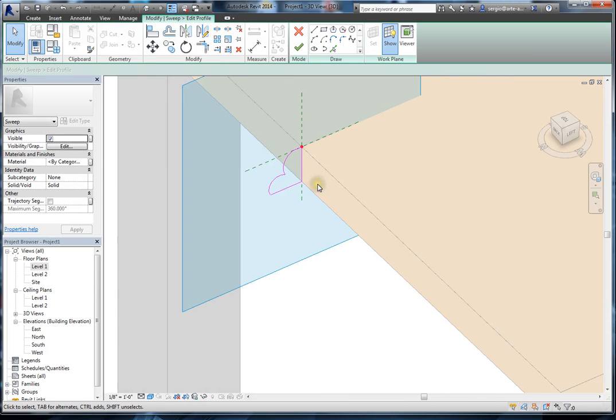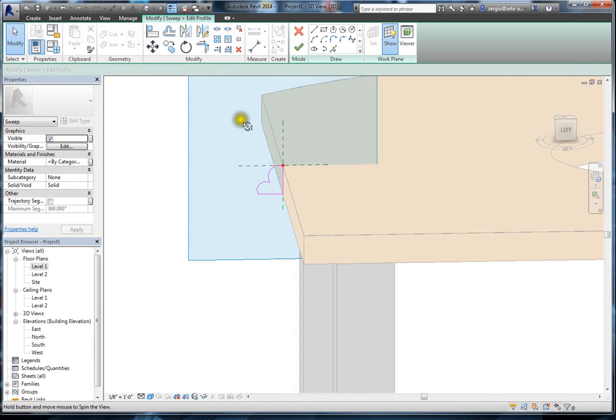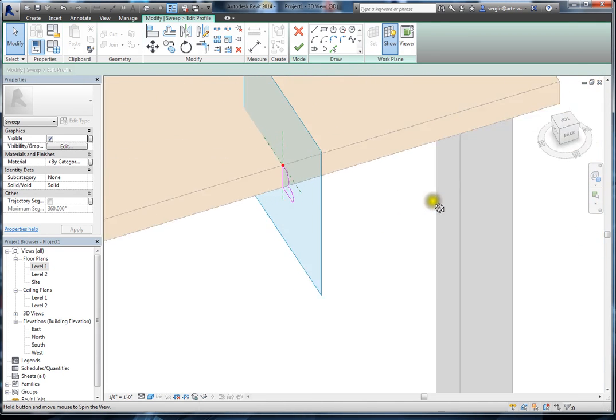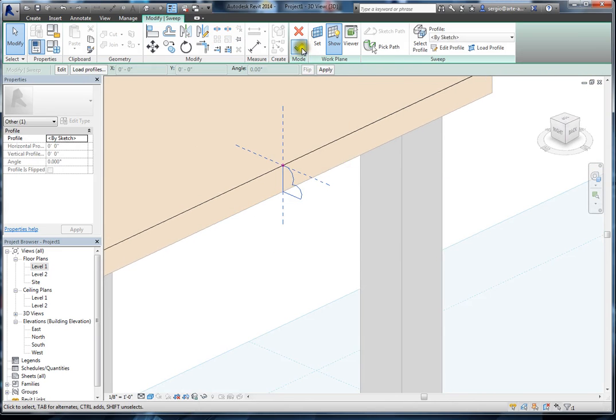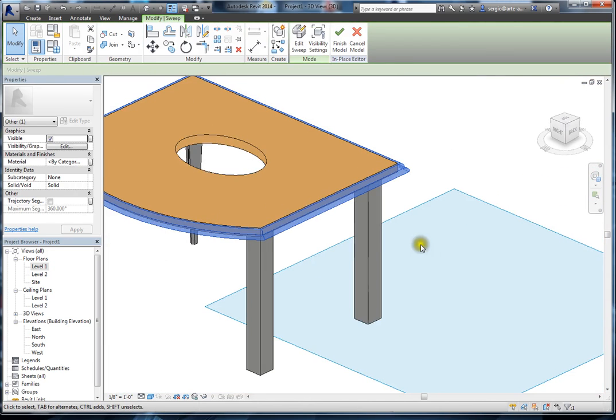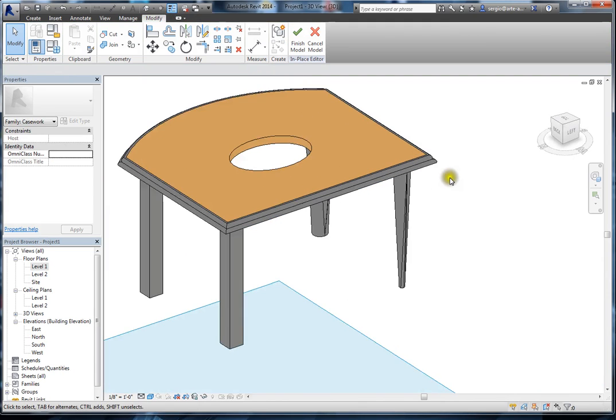Okay, let's say I want to shape a sweep around my tabletop that looks like that. Once I have a closed loop profile, I hit OK. One more time, and it creates my sweep around my table along the path that we identified in the shape that we created.